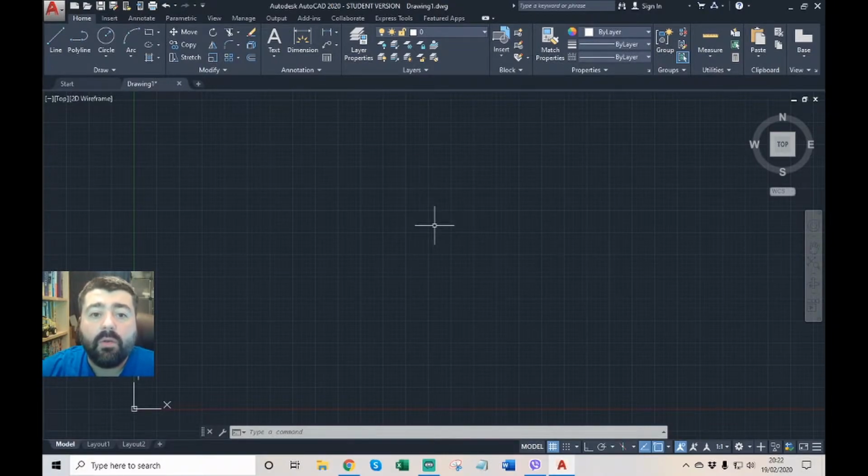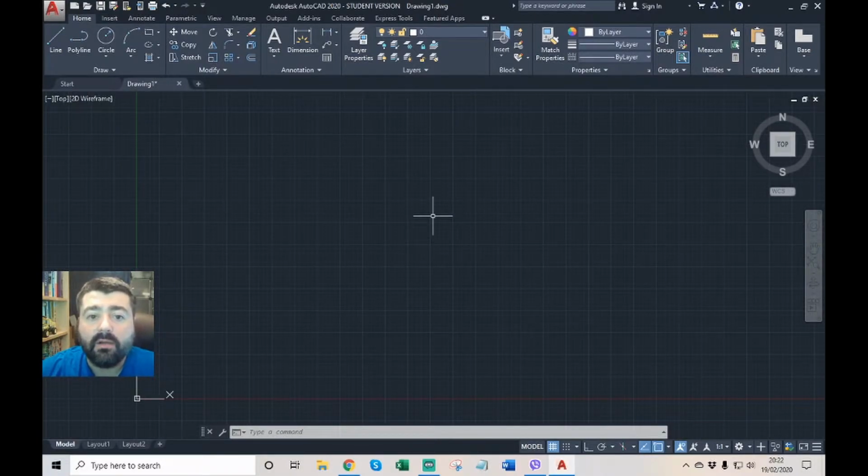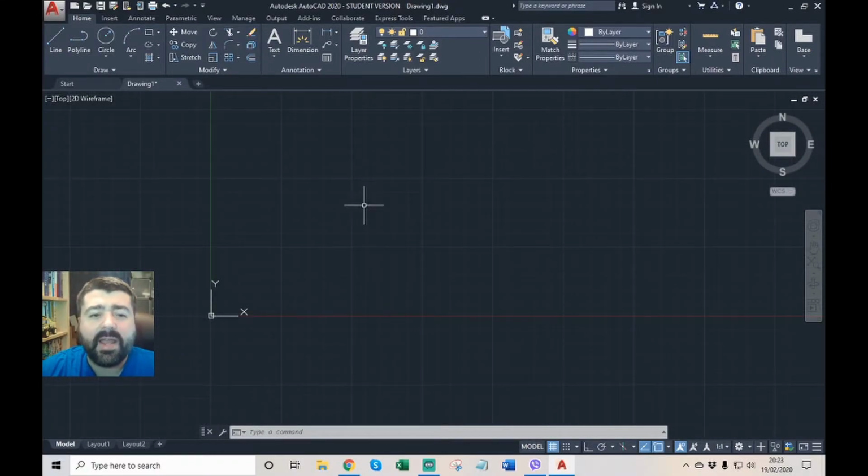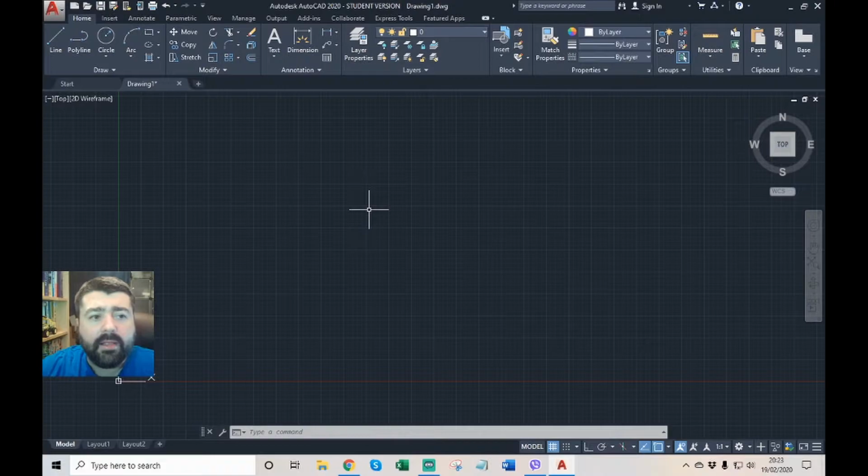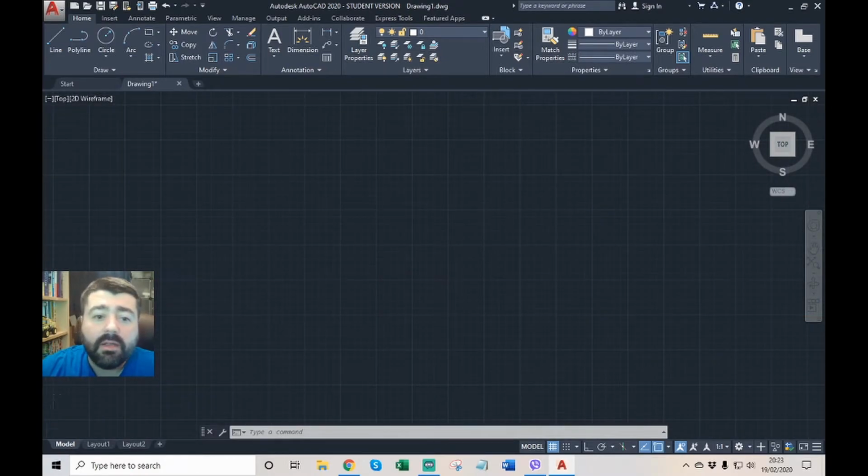So you draw it 1:1. So if your thing is 1 meter long, you draw it 1 meter long in model space. I'll get onto all that in later videos, into more things like scale and complexity. But so this is model space. It's usually black. Sometimes it's grey, but it's usually dark.